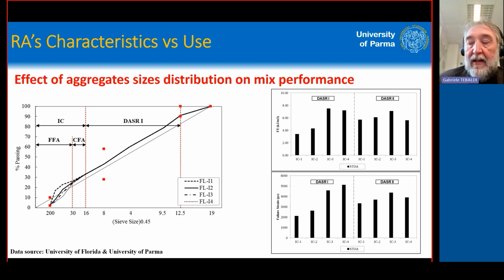If we work with less than 20% of RAP, we are in an amount of RAP that can induce a level of change that is inside of the variance of the test, something that is negligible. When we move forward and we go above 20%, with 30, 40, 50, and even more, as is now required by a lot of agencies, there is a very big risk that what we did in the mix design phase is not what we have in the field if we are not very accurate considering this element.